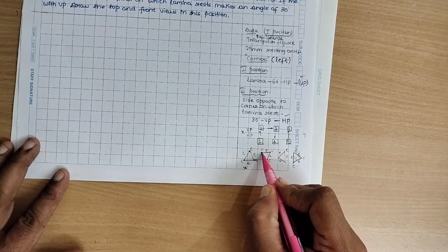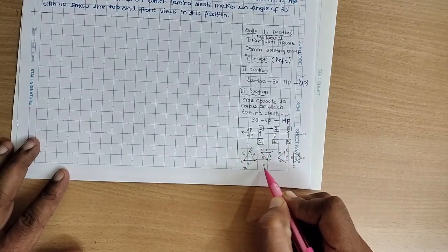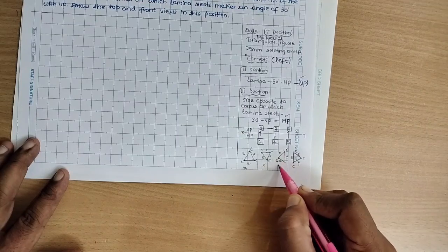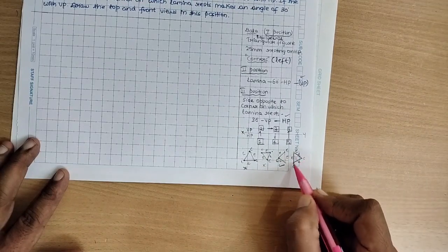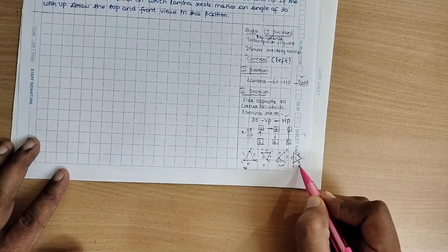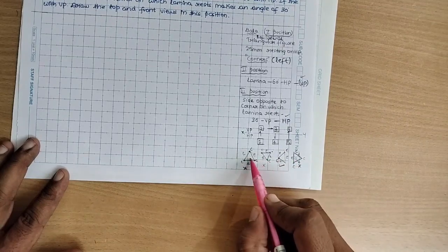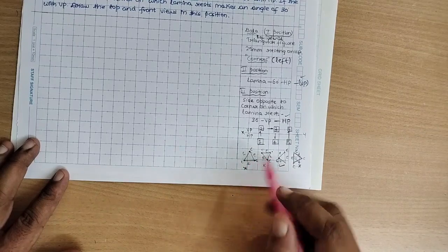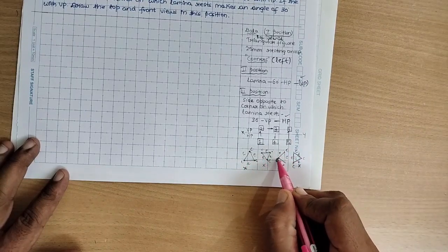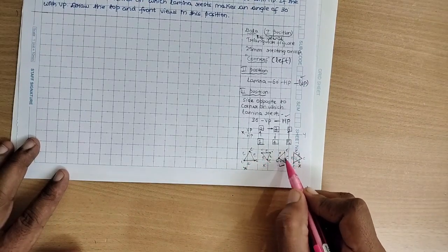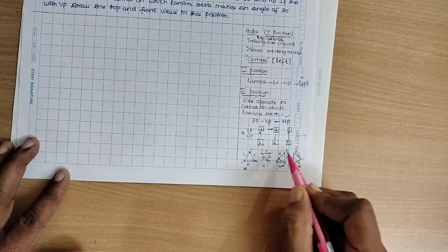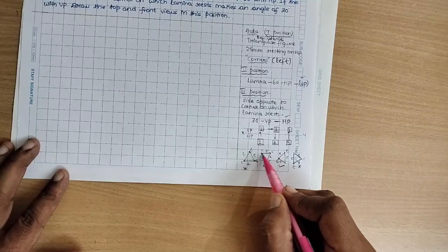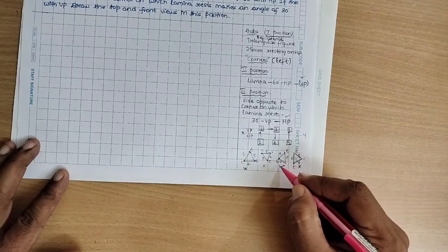This is also a corner. It can be considered, but let us cancel this one as well. But in this triangle, yes, we have a corner towards the left hand side. I will consider this one. This one is completely neglected because towards the left hand side we have the edge. A quick analysis: why are these two rejected even though there is a corner towards the left hand side? The condition says there is a corner, which means the opposite edge should make an angle of 90 degrees, perpendicular to the XY line. In this case there is no such edge. Here also there is no edge. So let us consider this figure.